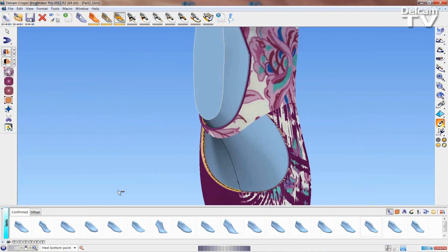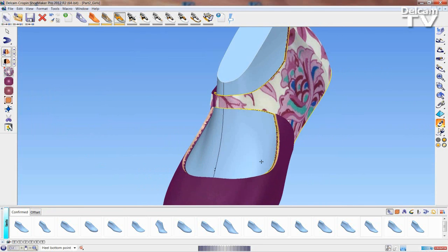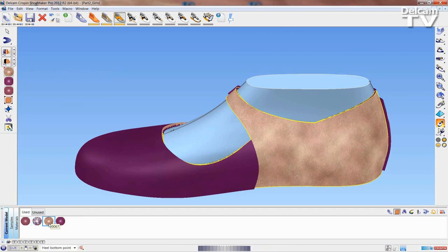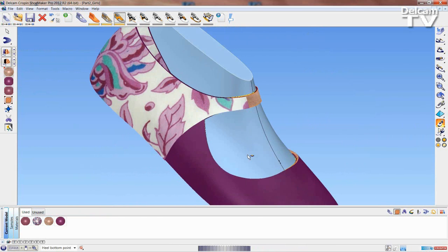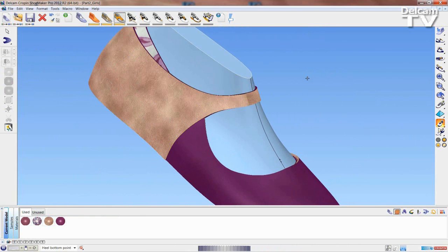Do the same for the lining on the inside. And then we can change the materials. Open the materials library and then use the materials from the current model section. We're going to set the outer face to the light pink colour, and then leave the inner face and edge face as they are. Do the same for the other set of lining, and then right click.